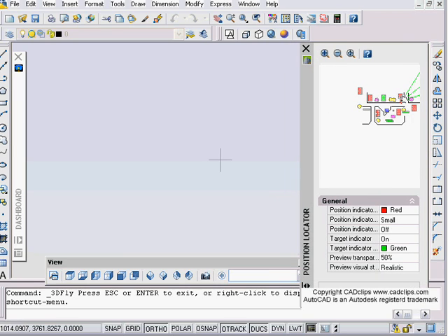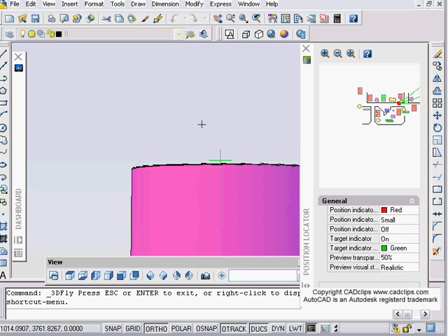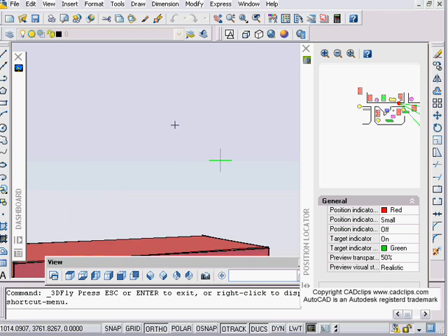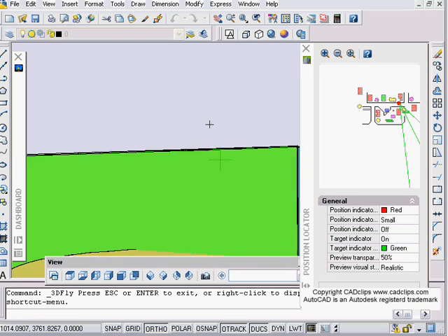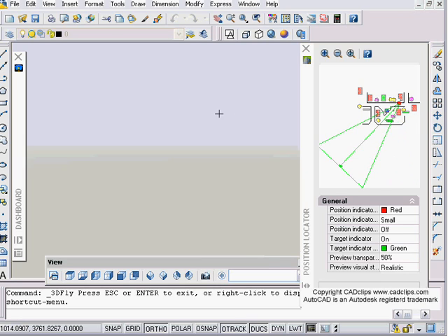and the thing that I've noticed is that if you try to fly and turn yourself around, it'll take forever. So the key here, sometimes I say, is zoom out, or what you can do to turn around is just take your mouse and drag like you're panning. Okay, notice over here you're turning around. I find to turn around you basically have to kind of stop and use your mouse to turn around.